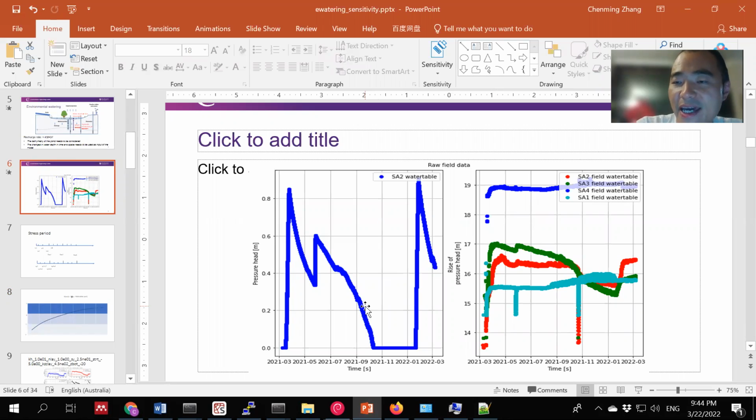It's probably 8:35, 9:35, 10:35. Now, if we create our model, we want to get just 12 o'clock every day, because the time step is 1 day. You will see that this discrete data does not give you the head at that point. So what we need to do is an interpolation. You have a few points and then you find out what the head roughly is at that specific time.